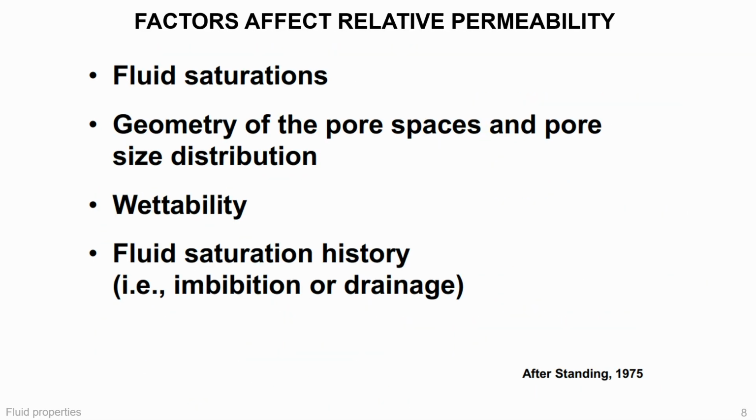Relative permeability is influenced by wettability, pore geometry, saturation history, interfacial tension, viscosity ratio, clay content, and heterogeneity. This is why relative permeability is often measured in SCAL programs rather than assumed. Teaching message: Kr curves are not universal. They must be rock and fluid specific.